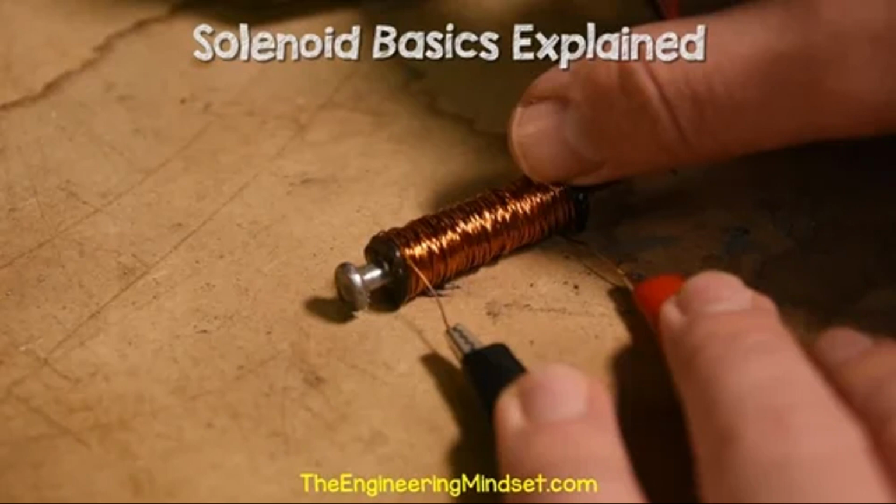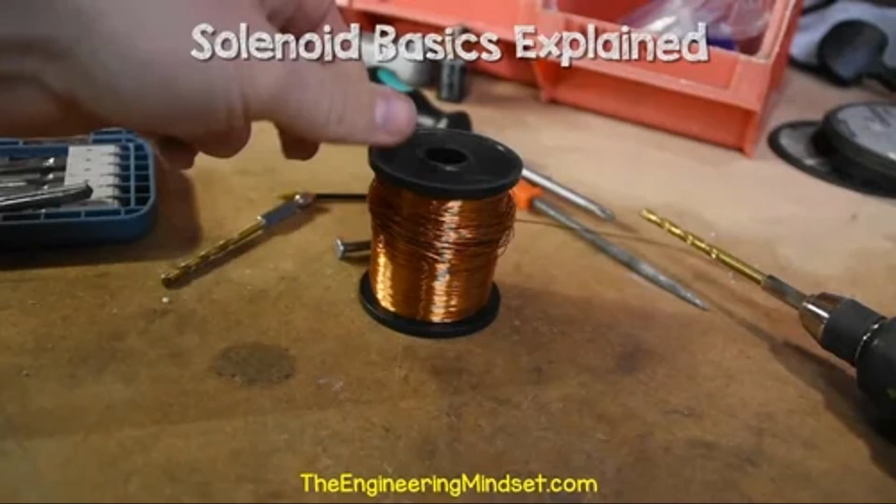Linear solenoids are electromagnetic devices that convert electrical energy into linear motion. They consist of a coil of wire wound around a cylindrical or rectangular form, with a movable plunger or rod located inside the coil. Here are some key points about linear solenoids. Construction. Linear solenoids typically consist of a cylindrical or rectangular coil made of insulated wire. The coil is wound around a non-magnetic or weakly magnetic form, creating a hollow space inside. The movable plunger or rod, often made of ferromagnetic material, is positioned inside the coil, either partially or completely.